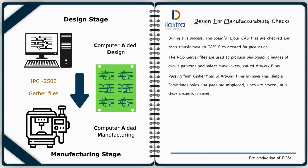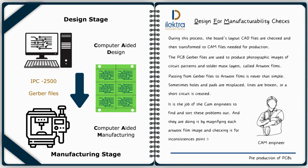Sometimes holes and pads are misplaced, lines are broken, or a short circuit is created. It is the job of the CAM engineers to find and sort these problems out. And they are doing it by magnifying each artwork film image and checking it for inconsistencies point by point.